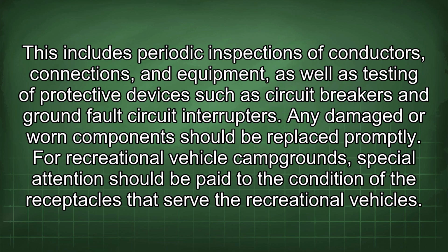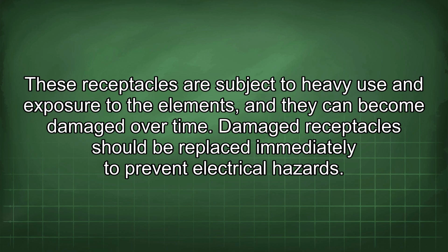For recreational vehicle campgrounds, special attention should be paid to the condition of the receptacles that serve the recreational vehicles. These receptacles are subject to heavy use and exposure to the elements, and they can become damaged over time. Damaged receptacles should be replaced immediately to prevent electrical hazards.